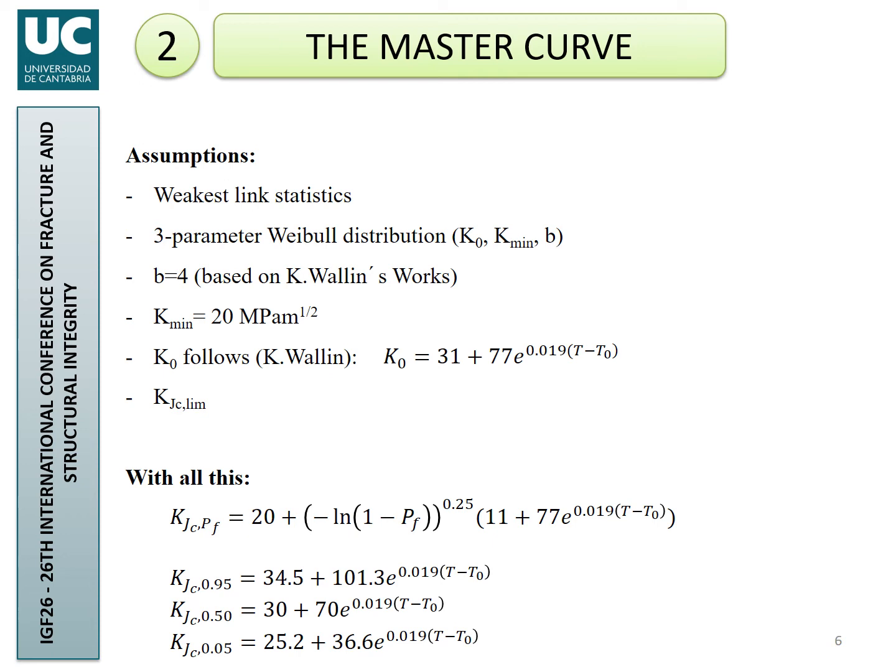And also, the master curve methodology establishes a censoring criterion, ensuring that small scale yielding conditions and high constraint conditions are fulfilled.